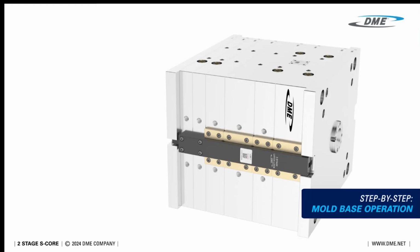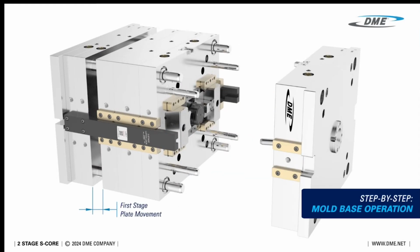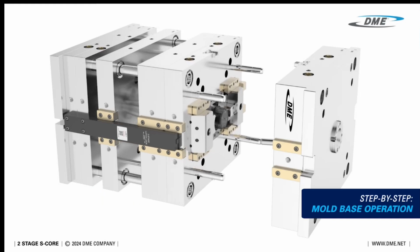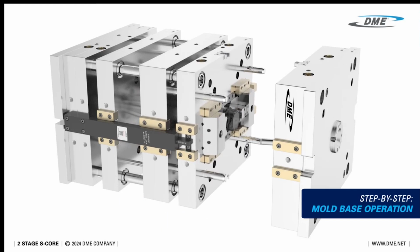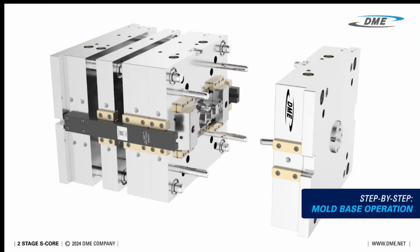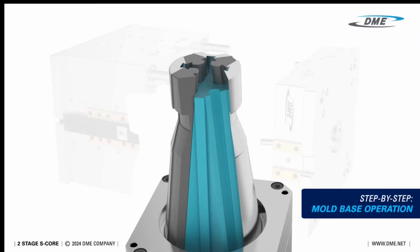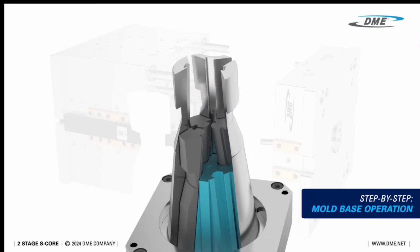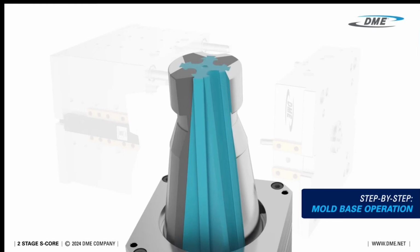Now, let's see the mold base operation in action. First, the first stage plates move, initiating the partial collapse of the core. Next, the second stage plates move, completing the core's full collapse. Finally, the stripper plate ejects the part from the mold, completing the cycle with precision and efficiency. This section view highlights the movements of the various segments within the collapsible core, showing how each component works together to achieve the core's function.